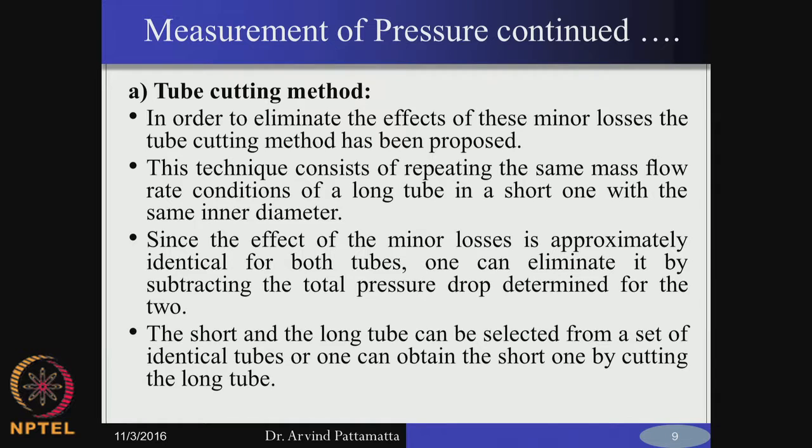So, there is nothing specifically problematic with using an existing differential pressure transmitter, which can measure the pressure drop for a bigger channel, for a microchannel. Usually only the range has to be customized, the ranges should be higher when you are going for a microchannel. However, there are other issues which make this measurement process a little bit more uncertain.